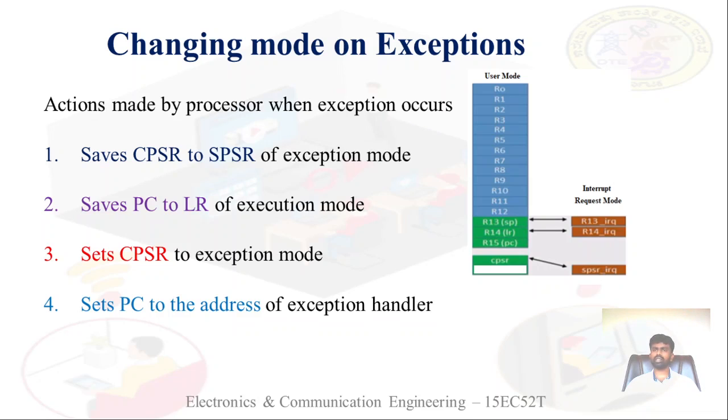Let us take one situation. The processor is executing in user mode, performing normal operation. At that time, suddenly an IRQ interrupt occurs. At that time, the processor should change the mode from user mode to IRQ mode.